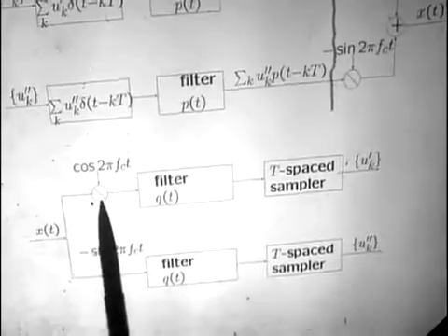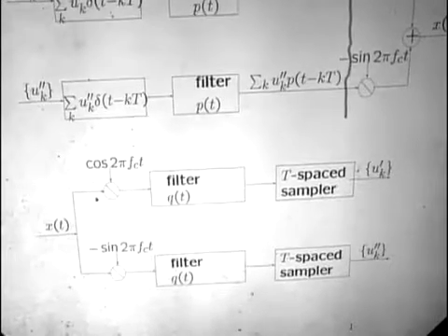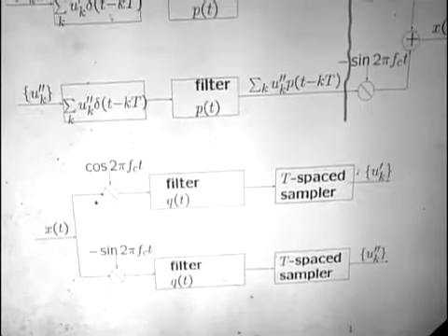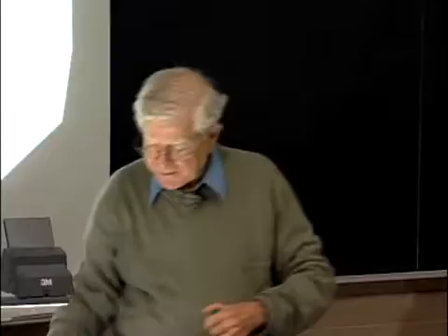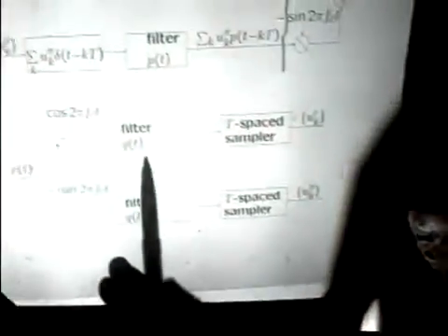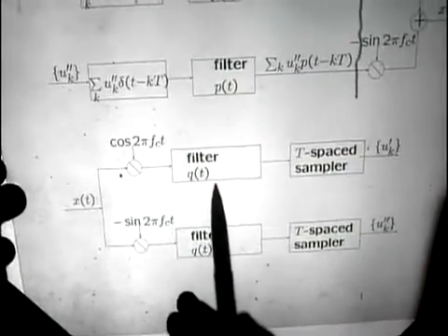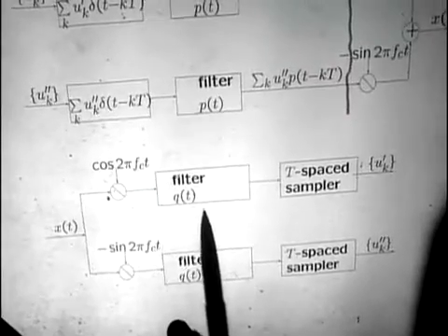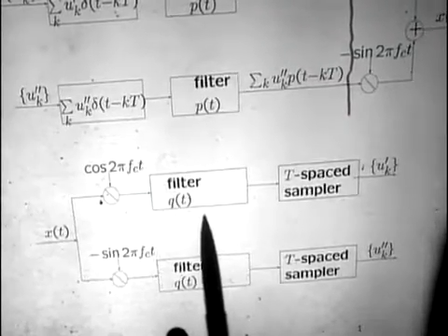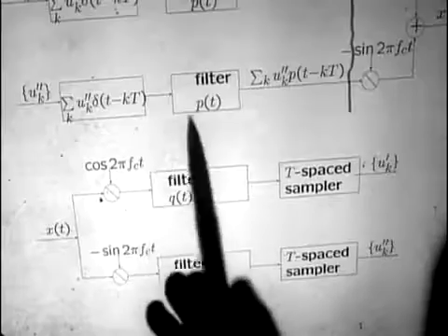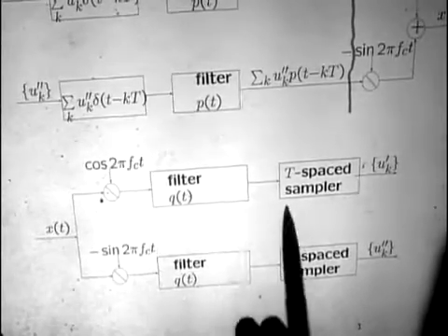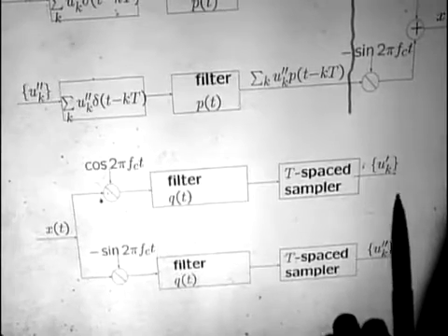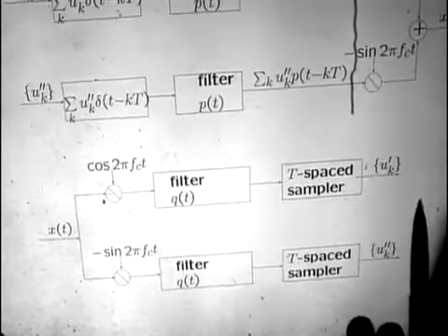When we get a cosine squared term, half of it comes back down to baseband, half of it goes up to twice the carrier frequency, and this filter, in principle, is going to filter out that part at 2 times the carrier frequency, and it's also going to do the right thing to turn it into something where when we sample, we actually get these components back again.